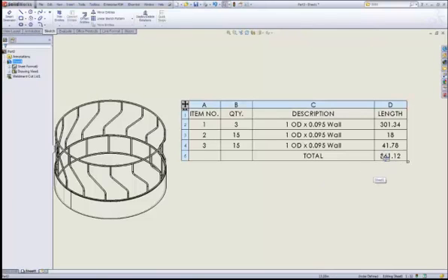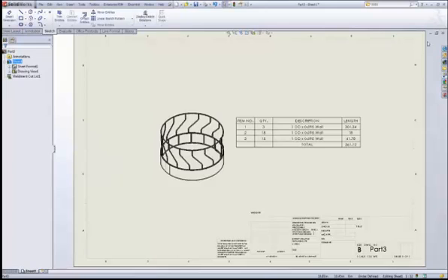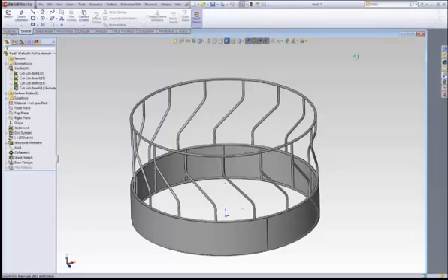Now, I've had a few issues with this, so be a little leery of this value when I update the lengths of those tubes. Sometimes that has not always updated for me, so be careful with that. Another way to know all the total lengths of your tubes is to create a drawing of the assembly. This might be the last thing that I can show. See, with this assembly document, I've got several weldment components. And there may even be other parts in there that are not weldments.